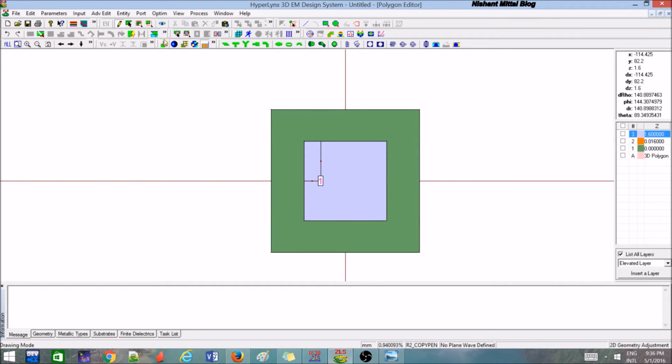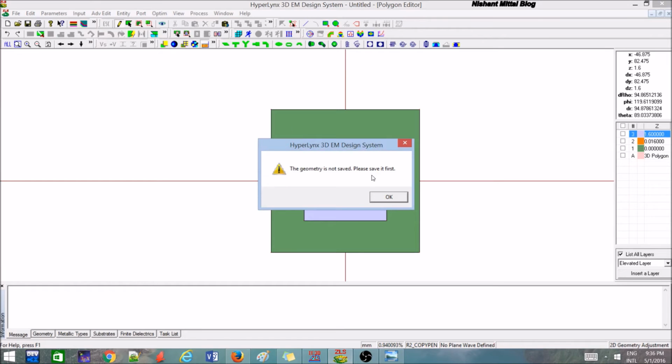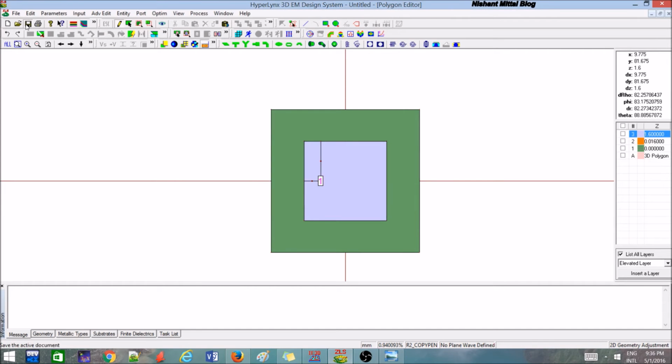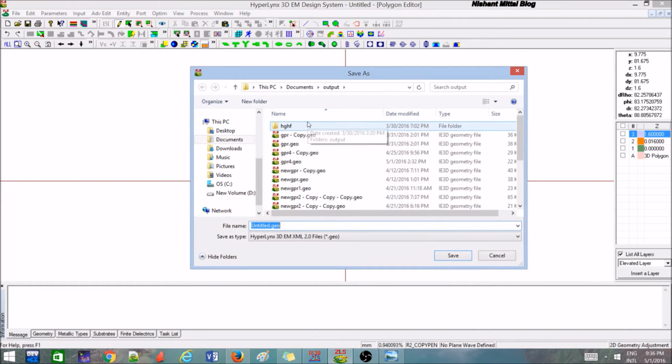All right, now what all is left? We need to declare the frequency. Okay, now since we have not assigned any frequency to it, using a general convention that a smaller length would have a higher frequency, I would give that simulation parameter over here. Okay, so before the simulation is done, we have to save it. So let's save it as tut2.